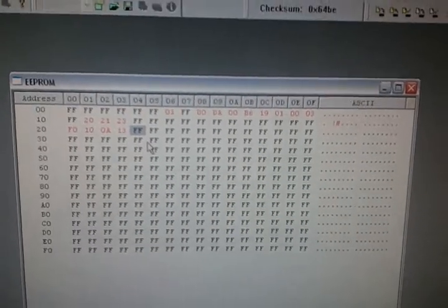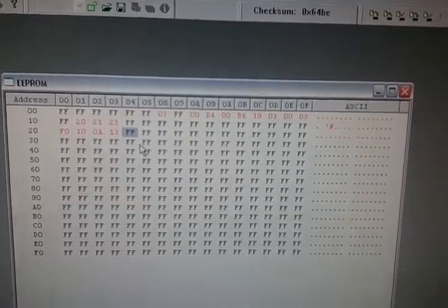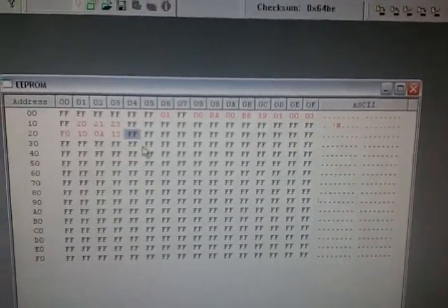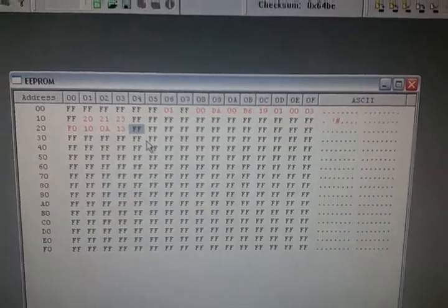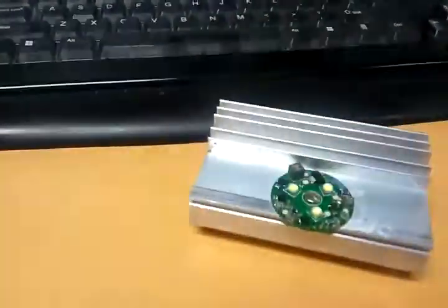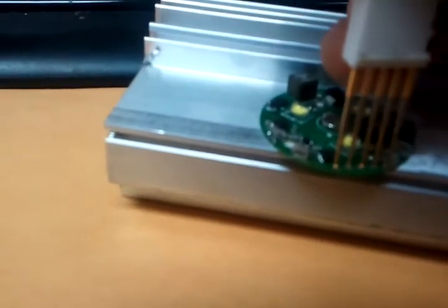This will be different for you based on which modes you choose, but if you happen to use the Mode Designer to make the exact same setup I just did, then it'll be all the same values. So that's all done now. We've typed in our mode assignments, and we can now go down to the module and take our PICkit and press it down onto those pogo pins.